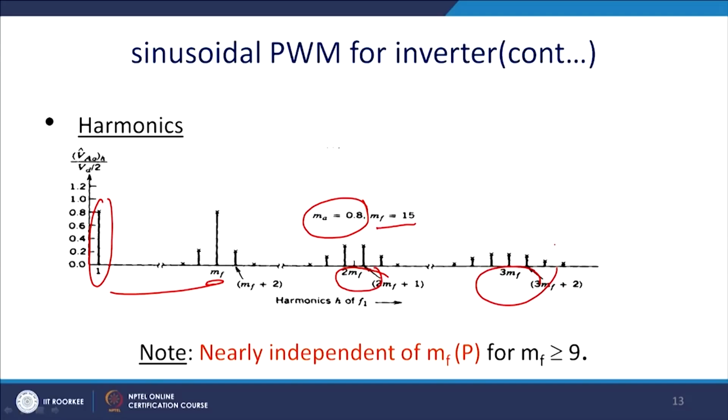Since it is actually very high frequency and lower order, it can be easily eliminated by a small low pass filter. The system, being a power system or drives, is inherently inductive, and thus it will eliminate this high frequency very easily.